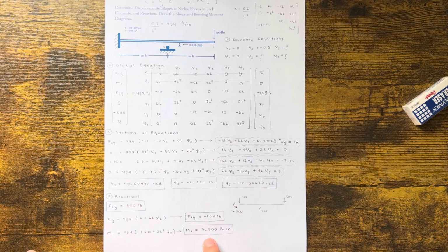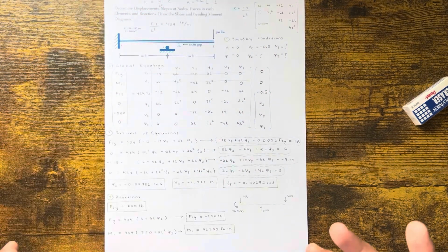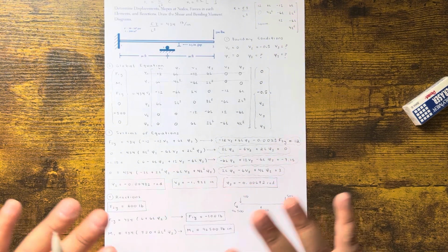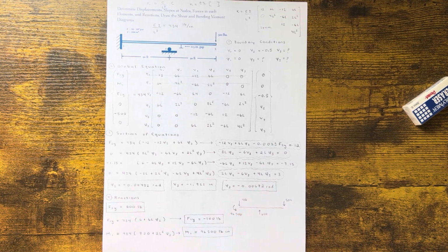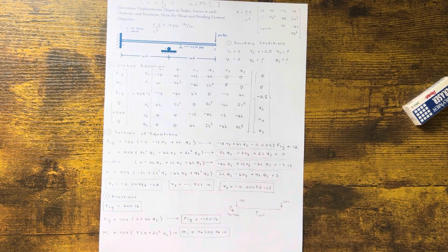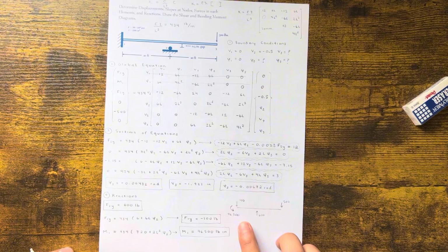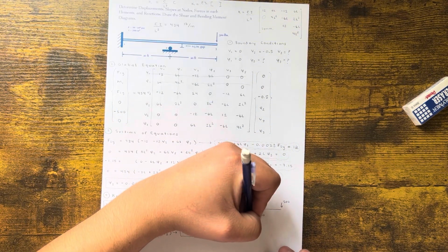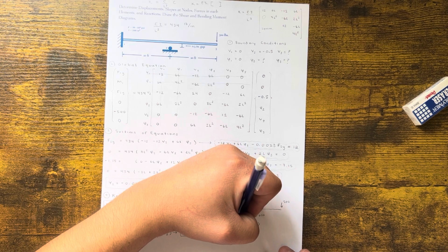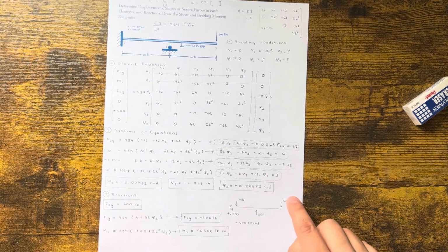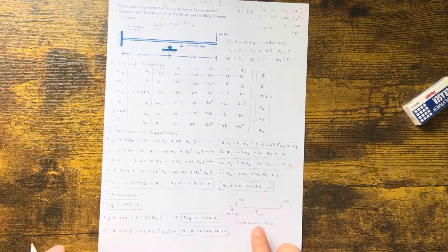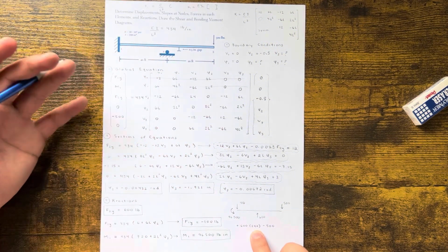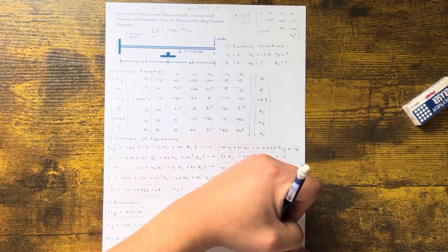Now you want to verify that M1 does have a moment. Remember, M2 is 0, M3 is 0. So you're probably tripping like some of the moments doesn't make sense. That's not how it works. Okay, remember. Let's do basic statics and just take a moment about point 1. Okay, node 1. 600 is doing a negative moment, right? Oh, I'm sorry, counterclockwise, so that's positive. 600 times 240, and that is positive, okay? Then 500 is doing a clockwise moment. So that means it's a negative 500 times the distance, which is 480, okay? 20 plus 20, that's 40 feet, times 12 inches each foot, that's 480, okay?